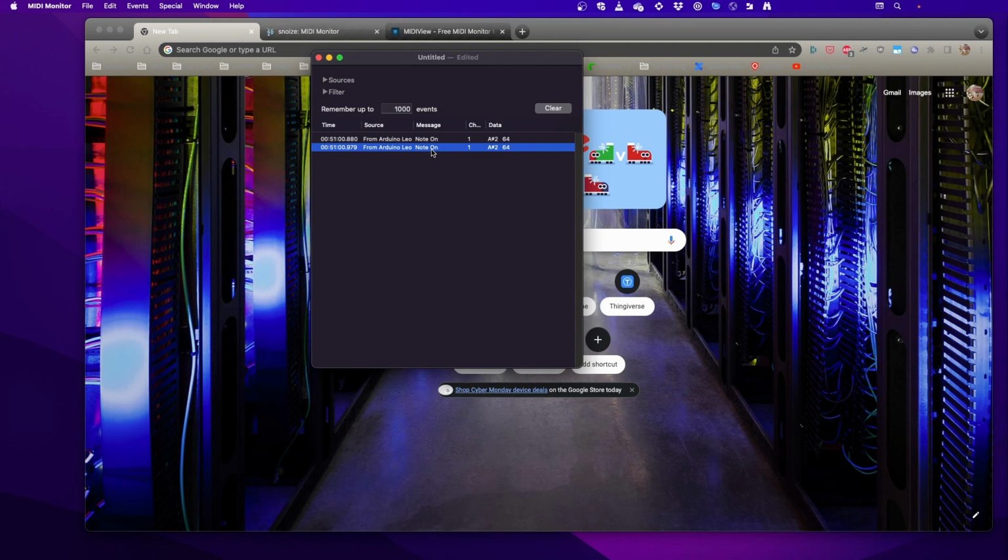Not to mention, here's the other issues. Little buttons that I have on this particular device, they're 9 millimeters tall, and I've noticed the taller ones have a larger tendency to bounce because they kind of move around a little bit. If I had a case and that was secured in a little hole, so you only had a little tiny bit to touch, it probably wouldn't be as bad.